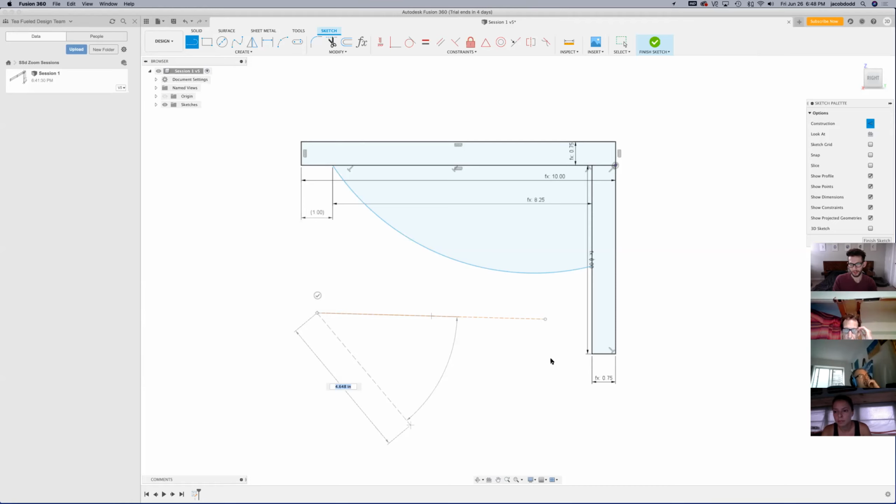So what we're going to use that for is we're going to make a line coming off of the backer board here, and we're just going to draw directly out perpendicular using the snap feature to make sure it's 90 degrees to that back edge. And this can be however long we want, because it's just for construction line purposes. Click the little green tick, and you can see if I press escape, it has the perpendicular constraint there.